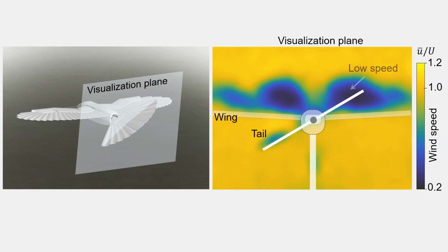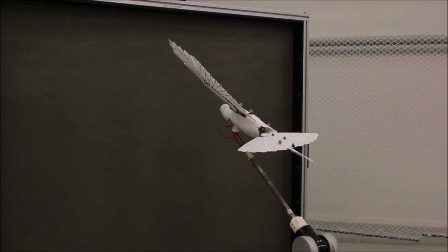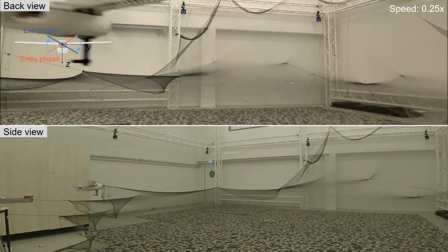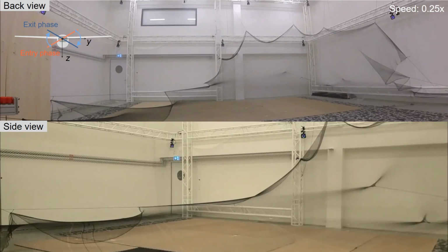We found that when twisted, the tail, located very close to the wing trailing edges, enters asymmetric flow regions induced by the wings. This results in the generation of asymmetric lifts on the two sides of the tail, therefore producing both roll and yaw moments to coordinate a turn. An experiment on a single degree of freedom gimbal showed that twisting the tail initiates rolling motion of the drone. Indoor flight experiments also validated that tail twist generates sufficient control moments to initiate, regulate, and end banked turns in our feathered morphing drone, and also in a fixed-wing drone.